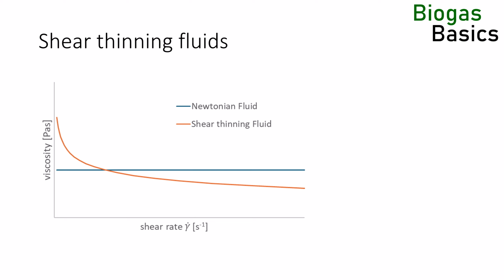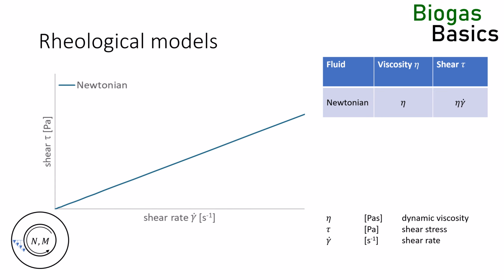This has significant impact on many phenomena at biogas plants. It is essential in the question whether stones and grit will drop out in the digester or be pumped out with the effluent. It explains overheating of submersible mixers and foaming events. There are 4 relevant rheological models I will use in this presentation. I will explain them with this plot of shear stress over shear rate.